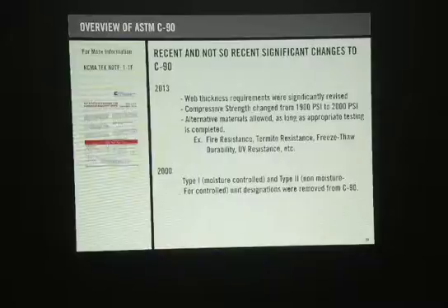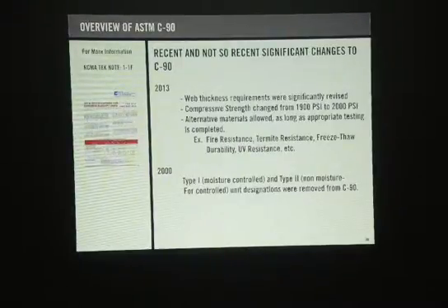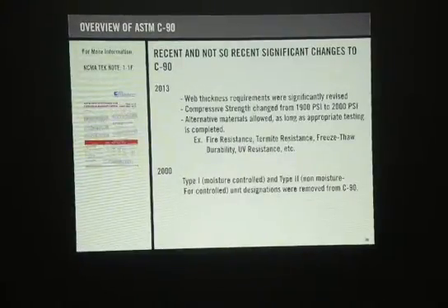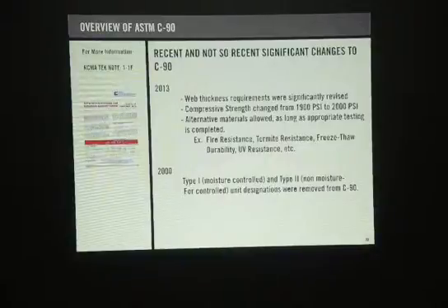temperature. Is that only if it is left exposed inside and outside, or does it not matter whether it's covered? If you do a furring on the interior side of the concrete block, inside the room, and then drywall, does that affect what you just said about the thermal? The furring will only help, because some people will use furring strips that are wood, other people will use metal furring strips.